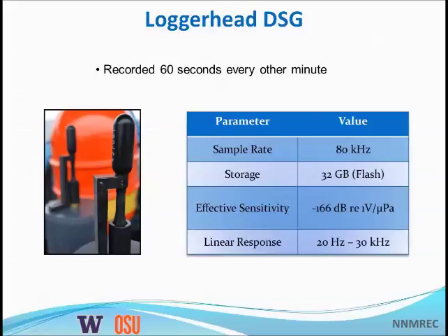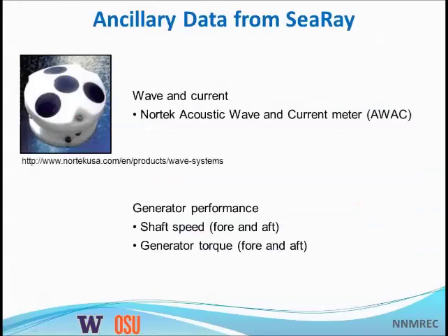The effective sensitivity of the hydrophone, when you account for the internal amplifier, is minus 166 dB with respect to 1 volt per micropascal. And finally, the linear response of this system is approximately 20 hertz to 30 kilohertz. So that's the range over which we're actually looking at some of this data. Next slide, please.